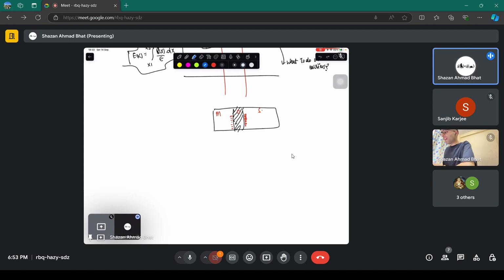respond under varying conditions. What I mean is that this particular structure, the MOS, is like a capacitor where there's an oxide. This is a metallic plate. This is the semiconductor system. You induced holes if you consider an n-type, and you have the electrons here.